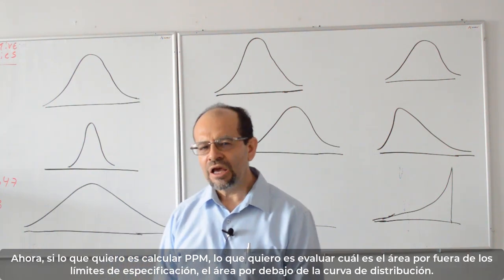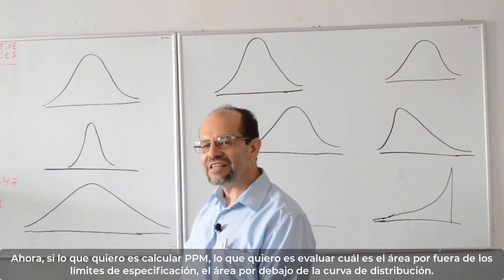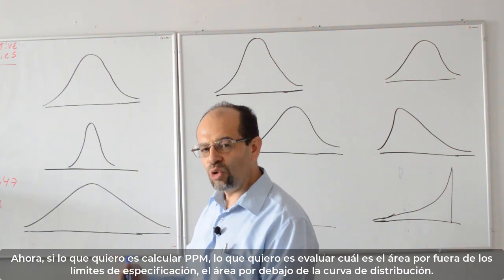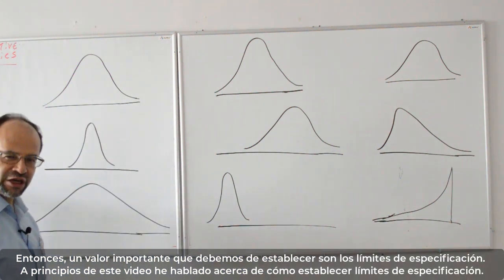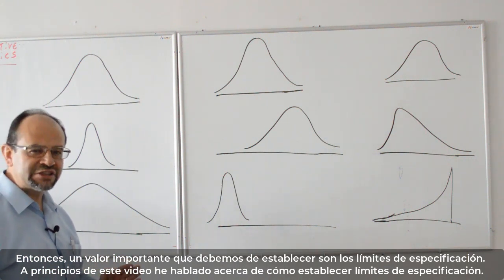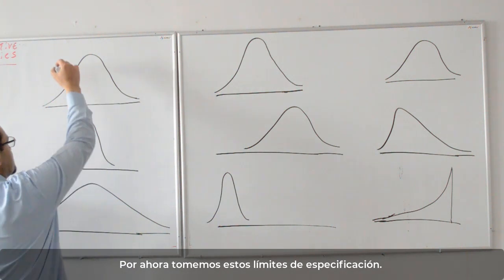If I want to calculate PPMs, I want to evaluate the area below the distribution curve outside the specification limits. Then an important value that we have to establish are the specification limits. In a different video, I'm going to talk about how to establish specification limits. But right now, let me just take the specification limits.